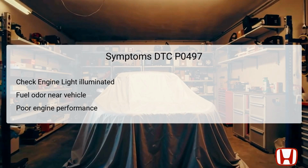One of the most immediate symptoms of DTC P0497 is the illumination of the check engine light, which serves as an alert to potential issues within the vehicle. Drivers may also notice a fuel odor around the vehicle, hinting at evaporative emissions leaking due to system failures.